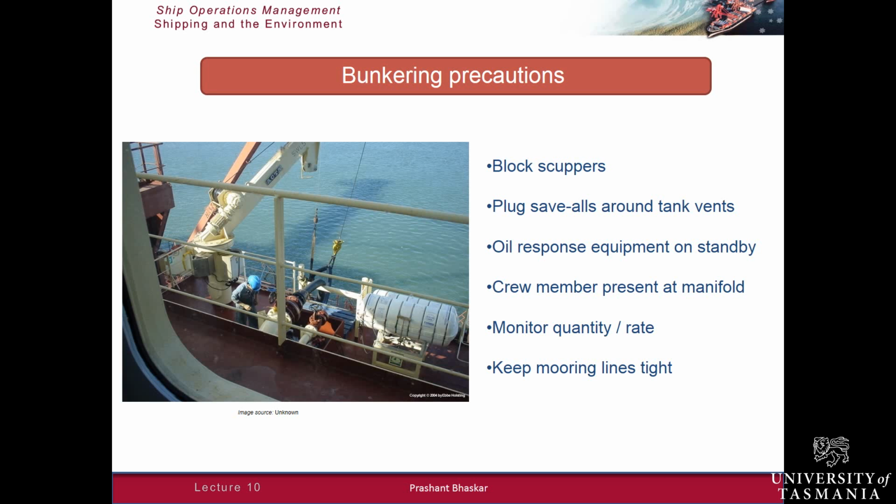I mentioned earlier that most of the oil spills are small in quantity, but they take place during routine operations such as bunkering. And if you think about bunkering, you can take very small, very simple precautions. So precautions such as making sure that if there is any oil spillage on the deck, it doesn't flow back into the sea. So you block the scuppers, making sure that tank vents have got drip trays or save walls, so that if the oil overflows, it would be collected by those trays rather than flowing everywhere.